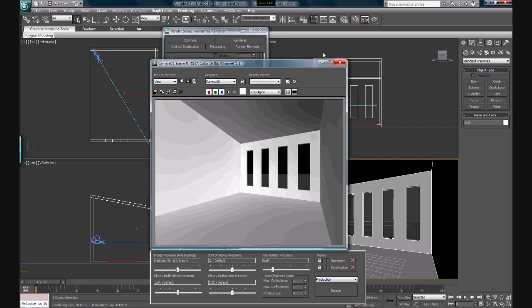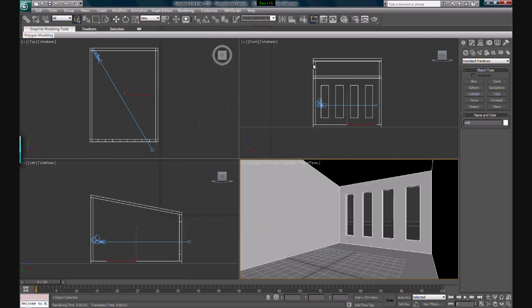So let's work on OmniLight first. Okay. So what is OmniLight? OmniLight works like a light bulb, where it spreads the light in all directions, as opposed to Spotlight, which has a focus point. So in order for you to create a light, you need to go to create panel and select the torch icon.